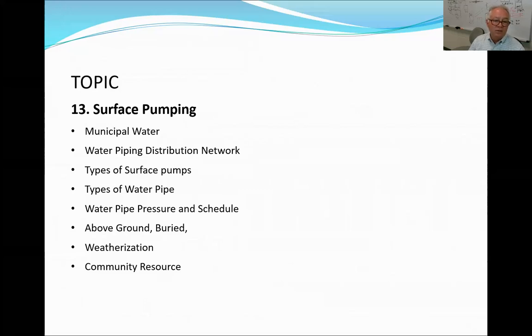And then here, this is where the surface pumps come in. They maintain the flow of the water and the pressure through the pipes. And then the pressure pumps and pressure tanks make sure that that water is always pressurized. And we're going to try to keep everything right around 50 PSI in our system that we build, and hopefully when we go to test it after we finish building it, everything's working properly.